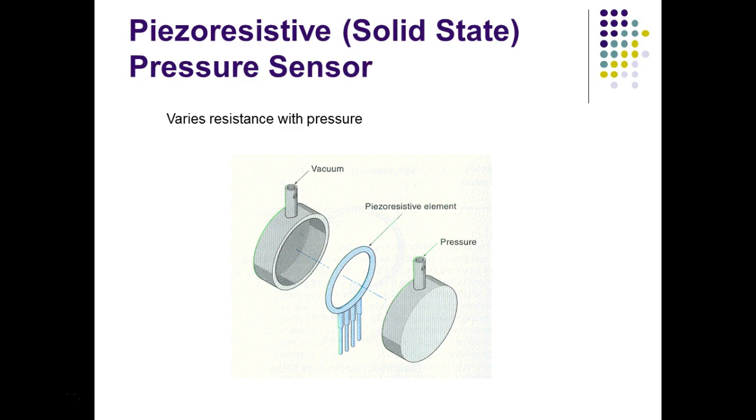And we use these a lot because they're solid state. There's no moving parts. So we've got a pressure sensor over there on both manufacturing lines. One of them is digital, but we've got an analog one over there too. Piezoresistive, I don't know, but all we know is they're pressure sensors, right? Pressure is a very important thing to measure. When you take the sensors class, we've got several ways we can measure pressure, but this is solid state, so all we're looking at is the semiconductor sensor, the solid state sensor.